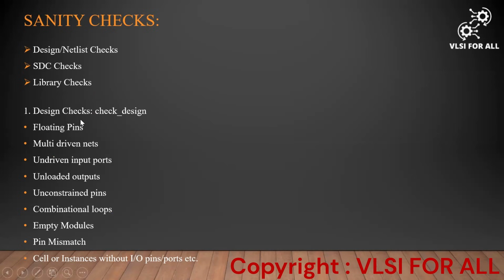Coming to the first one, design checks. To check the design, we have to use the command check_design. If any of the issues below are reported after giving this command, we have to report them to the front-end team, because if we proceed further with these issues, they will cause big errors or flaws in the further PNR flow.